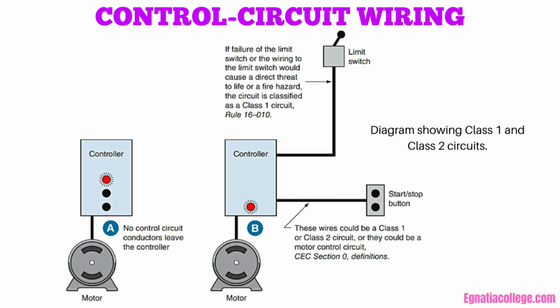Rule 26-804 and Appendix B give excerpts from CSA Standard C22.2 No. 3, entitled Electrical Features of Fuel Burning Equipment. Rule 4.8.8 of this standard states that a safety control shall interrupt the current in the ungrounded conductor of the circuit between the overcurrent protection and the load. This must be provided for in the control circuit connected to the Class 2 transformer.